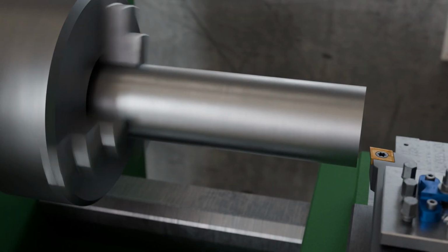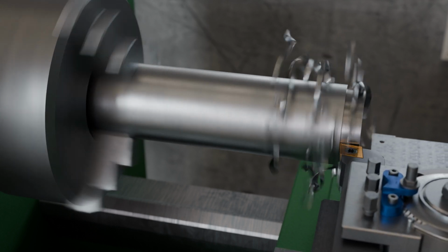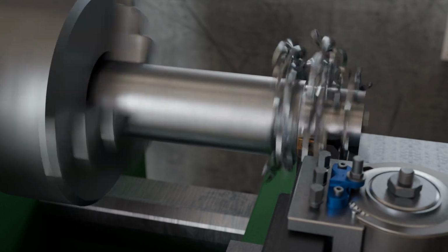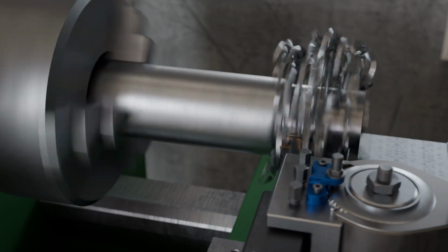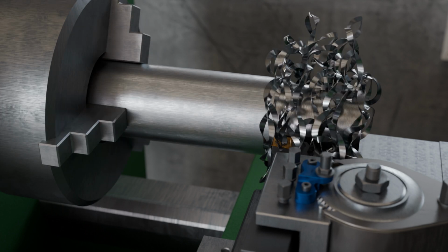Let's now turn to the previously mentioned free-cutting steels. In machining processes, long continuous or stringy chips must generally be avoided, as they can wrap around the rotating workpiece, especially during turning, and cause damage to the component or the machine. This is particularly disadvantageous in mass production on automatic lathes, where downtime may be required to remove tangled chips.